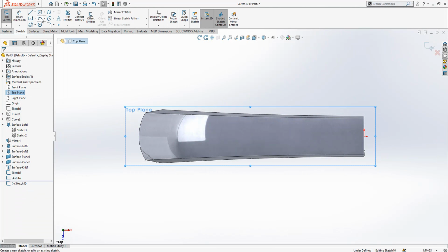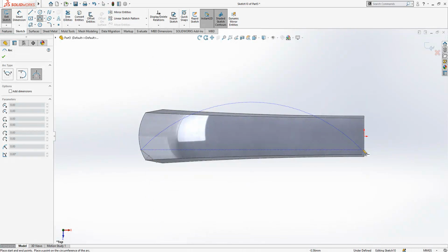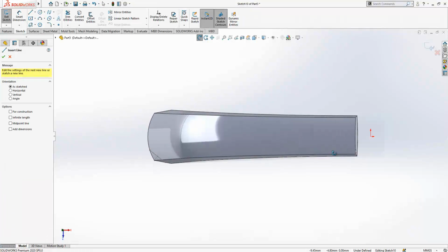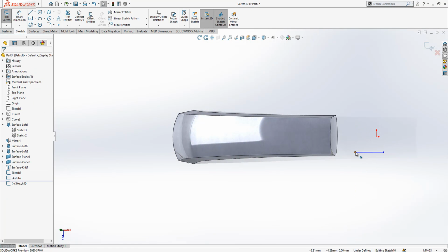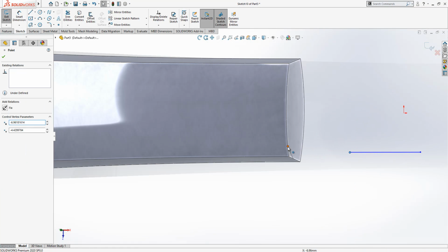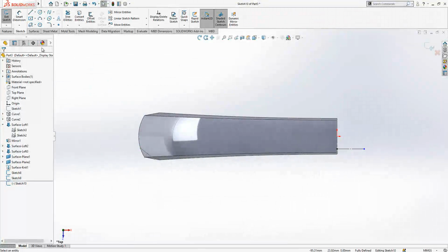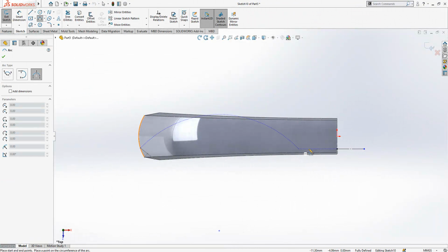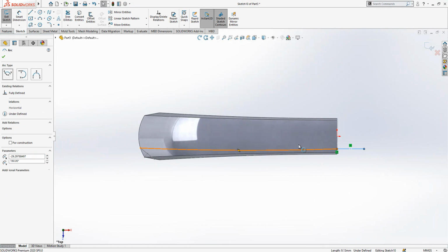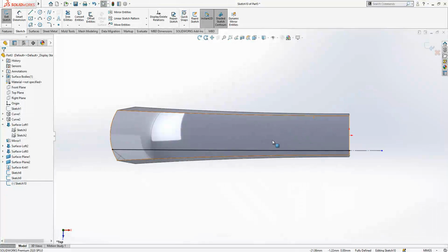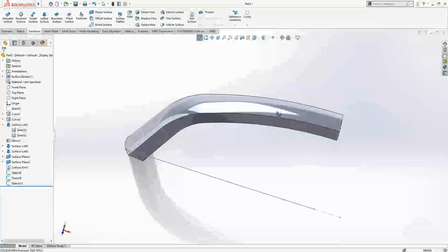Create here a sketch, an arc, something like this. But we needed again another sketch, another line in fact, to meet this point, where we can create a tangency to our sketch, our arc. These two points are looking fine. Right click, these two tangent. It's a tangent transition.